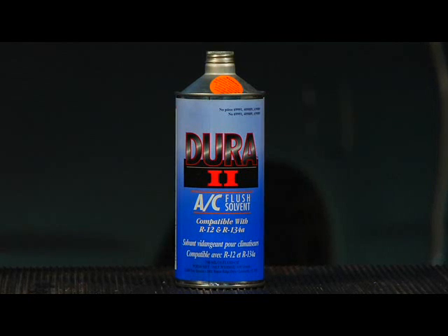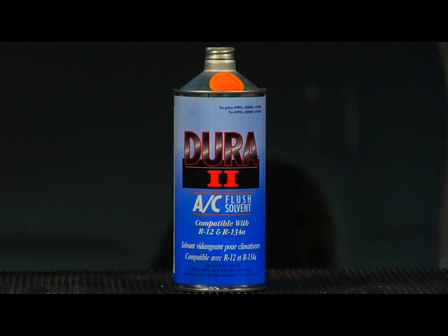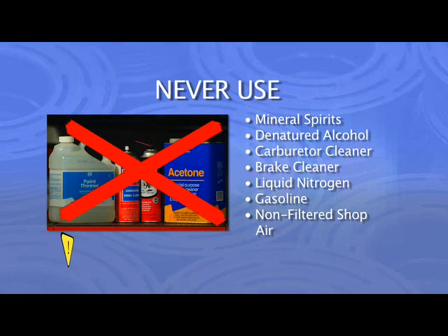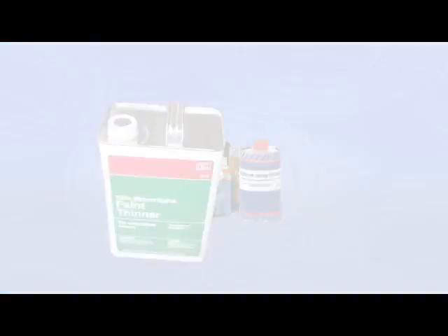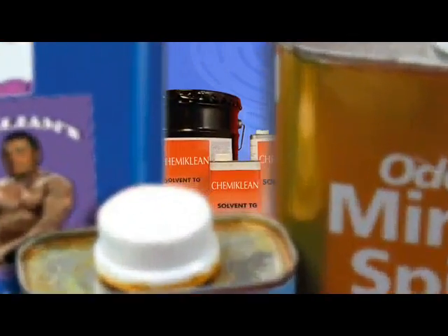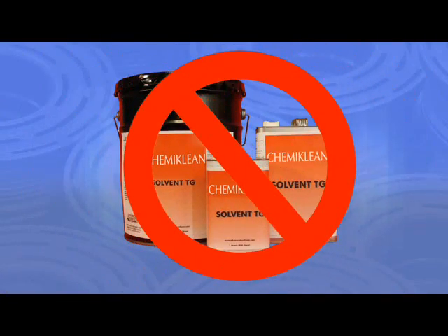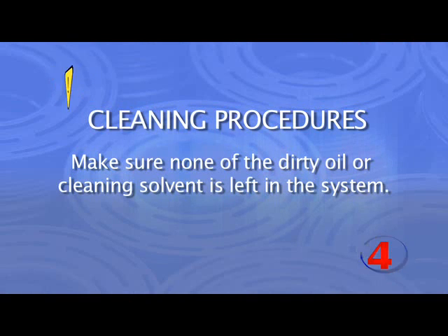We recommend Dura 2 solvent as it meets all of our requirements. You should never use mineral spirits, denatured alcohol, carburetor cleaner, brake cleaner, liquid nitrogen, gasoline, or non-filtered shop air, or any other solvent not approved by the manufacturer. When using solvents to clean components, you must make sure that none of the dirty oil or cleaning solvent is left in the system. Proper cleaning procedures must be followed to ensure removal of all debris.